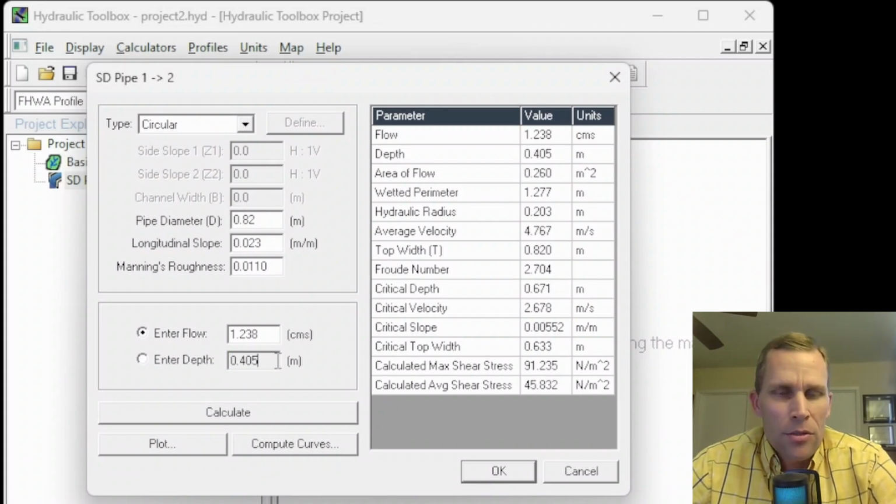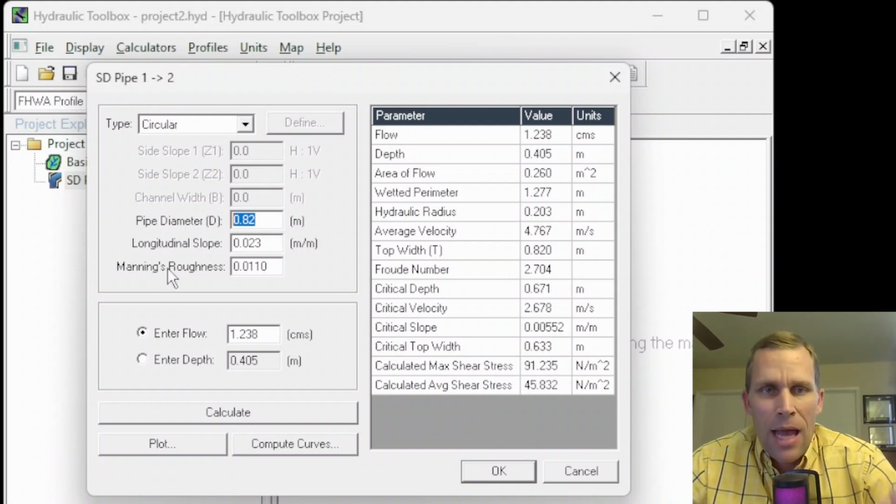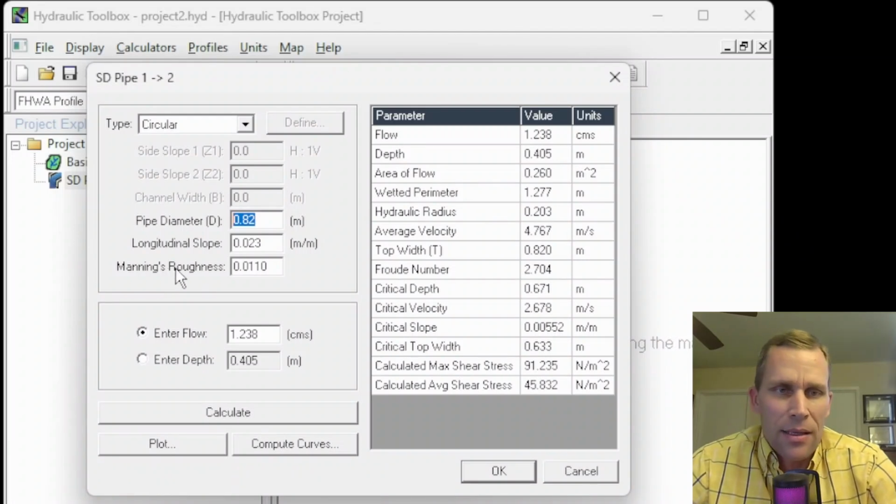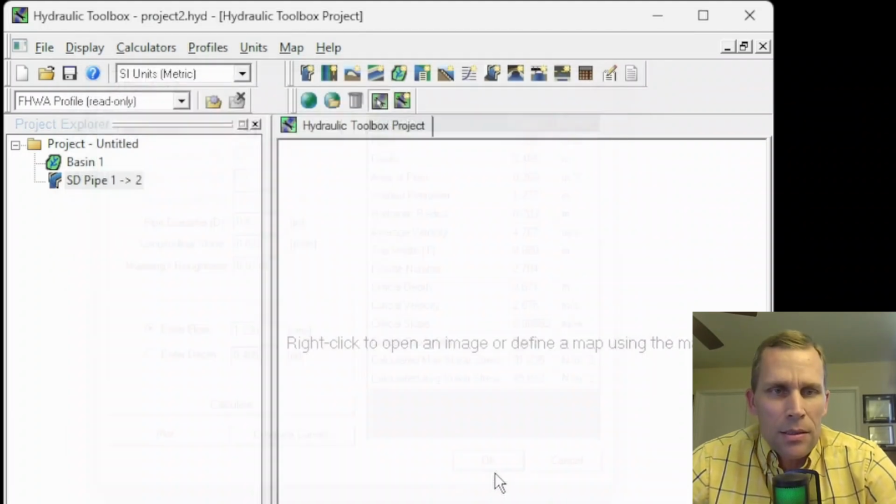Okay. So that is our answer for the first half, the first type of the two pipes. Diameter D12 is going to be 0.82 meters or larger because in reality, manufacturers probably don't have custom pipe sizes like this. You'd probably just round up to the next size, which is, I don't know, 1 meter, maybe a 0.9 meter available. I'm not sure. So I'm going to close up this calculator.